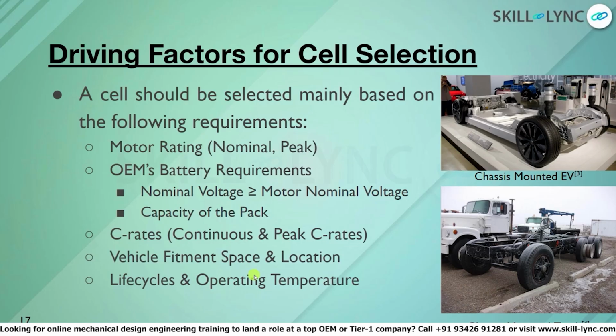So this is how a cell is defined. When the cell is rated at 0.5 C or 1 C, the life cycles say are 3000. That means if you charge and discharge the cell at 0.5 C or 1 C, only then will you get 3000 life cycles, otherwise you will not get those kinds of life cycles at all. That is how the life cycles of a cell are arranged.